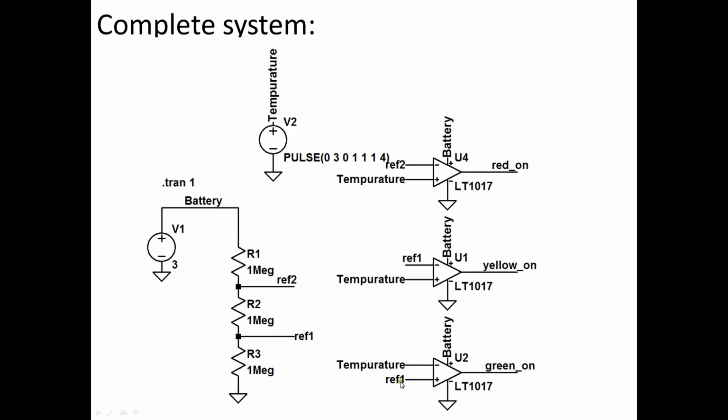Now for the green one, I have Vref coming in on the positive and temperature coming in on the negative. So that means when Vref is greater than temperature, this will turn off. And when it's less than the temperature, it will turn itself on.